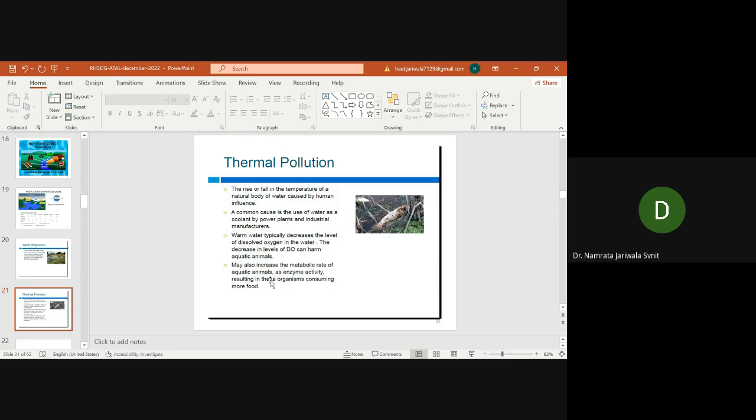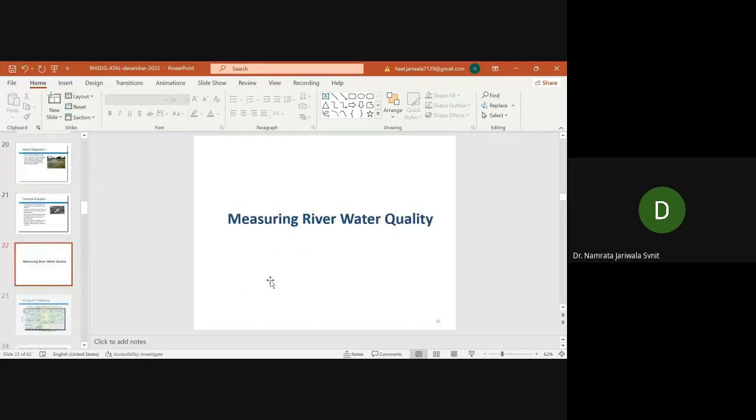And because of that, the temperature of the water bodies, whatever we are considering, changes when they are diverting the wastewater, which has a higher temperature. That will deplete the dissolved oxygen available in the water bodies. And that is why we have to consider this, because when your DO is going down, ultimately that may create a problem as far as aquatic life is concerned. As DO goes down and down, there will be anaerobic conditions that may create an odor problem.